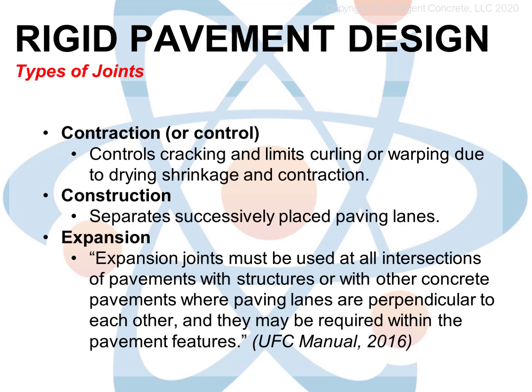Construction joints are usually spaced to line up with our contraction or control joints, so they are usually not a visible component after construction. Expansion joints are used when a pavement butts up against something that is not a pavement, or perhaps another pavement going in a different direction.